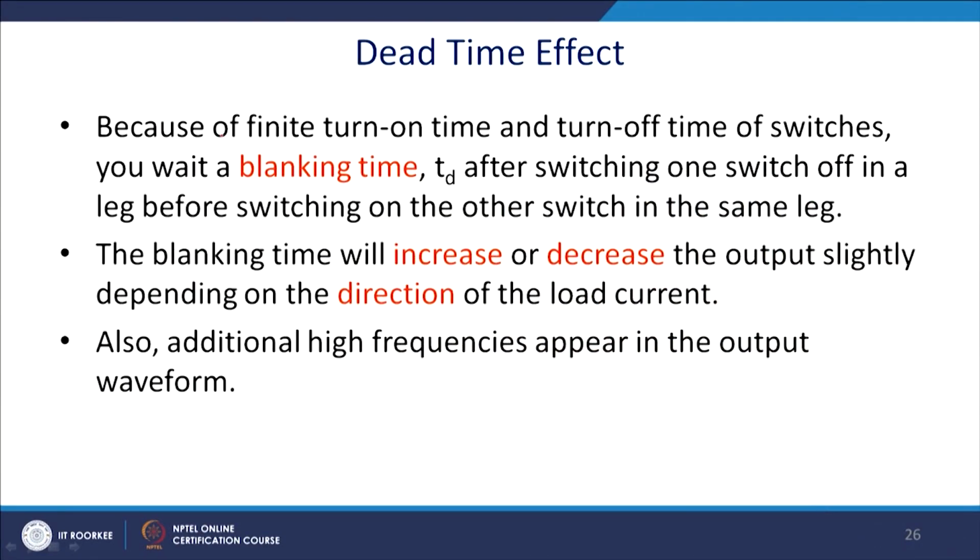So, because of the finite turn on time and turn off time of the switches, we wait a blanking time Td, and this blanking time slightly increases and decreases the value of the load current. In addition, some kind of high frequency may appear in the system. We can say that blanking is a necessary evil. We require to provide blanking for safety and security, but due to that a few phenomena will arise. Ultimately, your control circuit is required to rectify those problems.